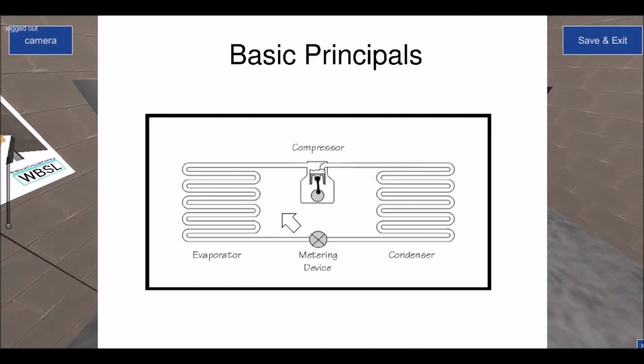And then when you're using things like a capillary tube, which you would normally find on a domestic system, we would ensure that there is what's known as a critical charge. In other words, the exact amount of refrigerant that is required to remove the heat that we have calculated in the space that we're trying to cool is in the system, and not any extra and not any less. It's a critical charge, so we have to have the exact amount in it.